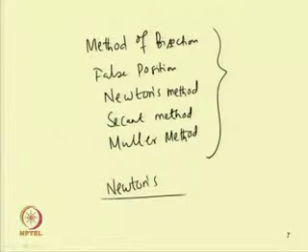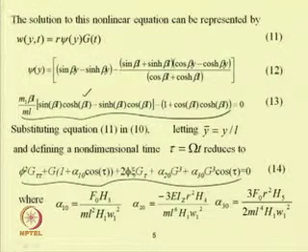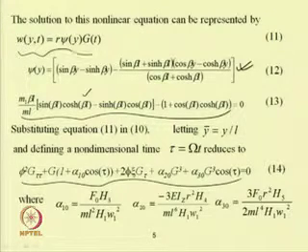After finding the roots, one can find the shape functions of the system. Using this beta value from the characteristic equation one can find the shape functions, and then use the shape function in the approximate function, where r is the scaling factor, psi of y is the shape function and g of t is the time modulation. Then one can apply the Galerkin method to reduce this spatio-temporal equation to its temporal form.